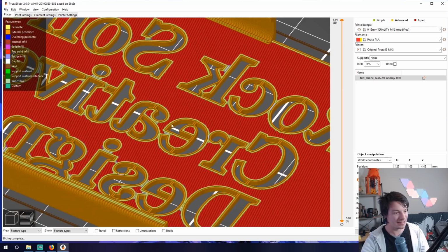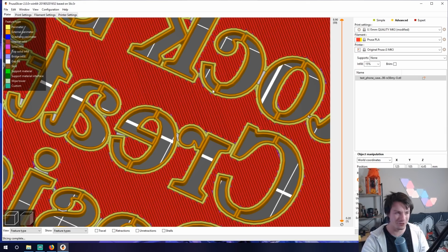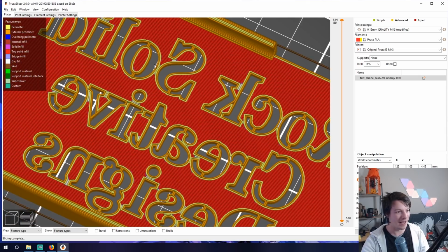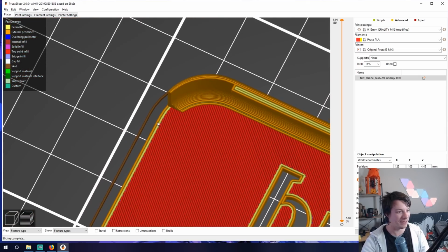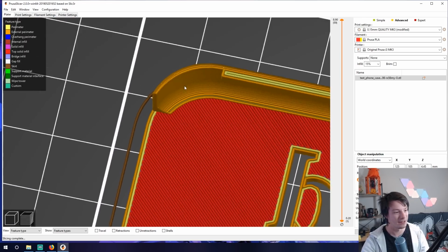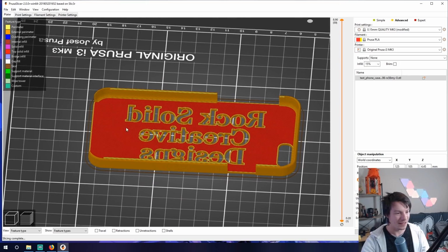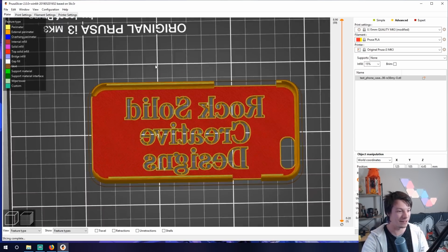Alrighty, so here we go. So see what I mean about the very thin areas? These little bits on the stencil are just 2 extrusions, very, very thin. And the actual case has been well designed, but you can see here, it's actually had to collapse down to single extrusion lines for the lip of that case. Very, very thin. And I haven't changed the speed settings or the layer height settings. It's still the default quality for the Mk3 at 0.15mm layer heights, which I think is very important.